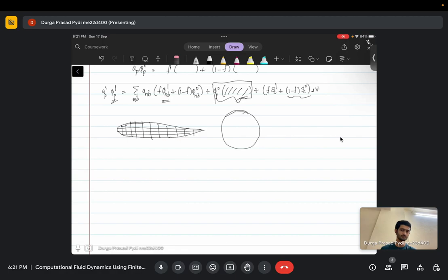Okay, let's say, for example, instead of taking these complex geometries, let's assume it's a rectangular domain, and I solve it using structured and unstructured meshes. In this case, which one will be more accurate? Your structured one should be more accurate because unstructured has introduced some approximations. But if your Gauss-Seidel is converged, then both of them should give you the same result. After convergence, the result will be the same for both. Whenever you use the secondary gradient in all these terms, you are just changing the weight to your final solution, but the final solution remains unaffected.